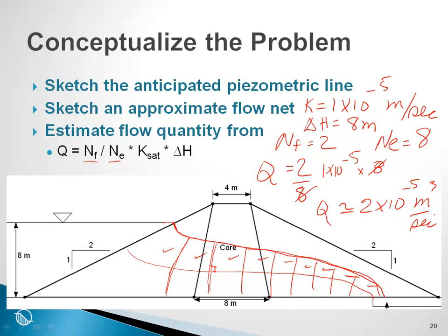It is incredibly important in numerical modeling that you are able to have some mental picture of what the solution should look like before you start the finite element analysis. If you cannot conceptualize what the solution might look like, then it is very, very difficult to interpret the results. So once again, not to bore you, but I would suggest you go to the folder Papers of Interest and read the 2 papers there on the methodology of good modeling practice.